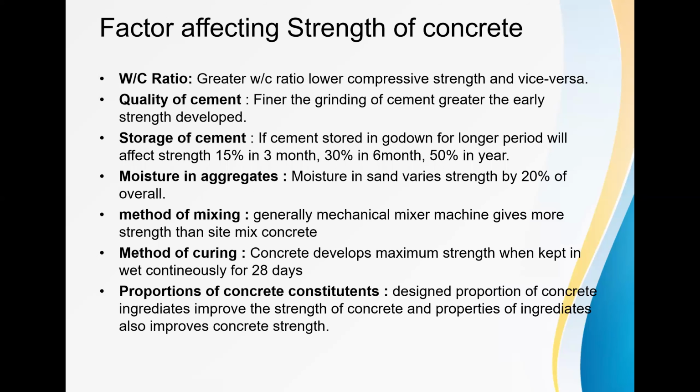Then what are the factors that affect the strength of concrete? First is the water cement ratio. The greater the water cement ratio, the lower the compressive strength, and vice versa. Then is the quality of cement. The finer the grinding of cement, the greater the early strength developed.